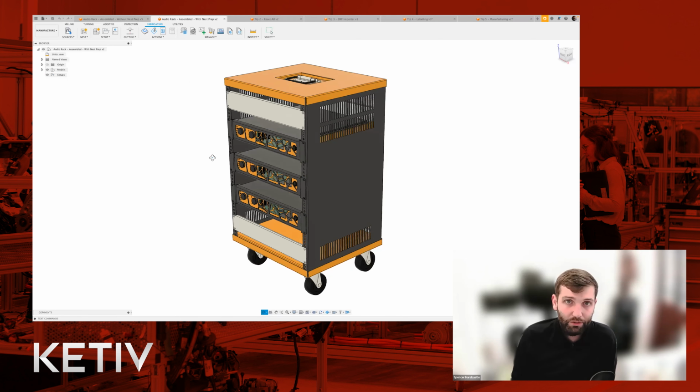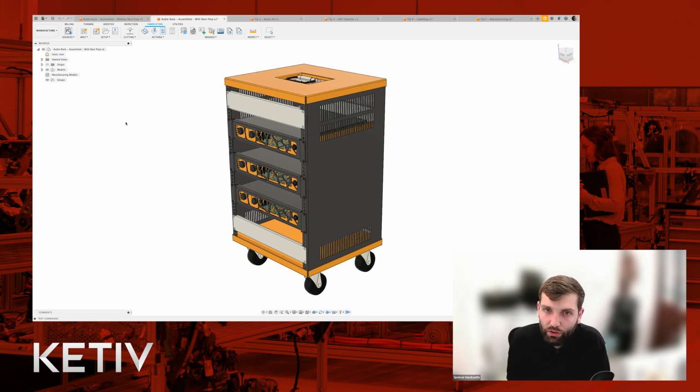It's in terms of time as well. The opening time of component sources really does go a long way. And I said it affects everything. Let me just pull up component sources here real quick, and I'll show you exactly what I mean. This is the first time I've clicked it, so it's going to calculate each of these materials. It's going to calculate the nestable shape of each of these, and then bring up a dialog that allows me to fine tune each of them.